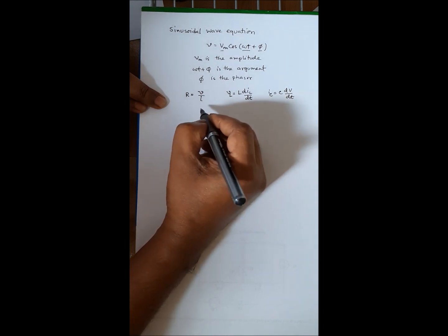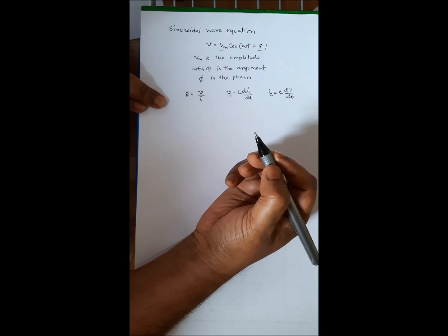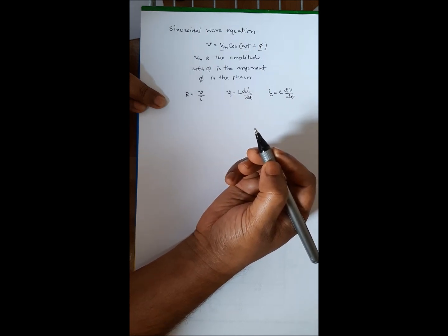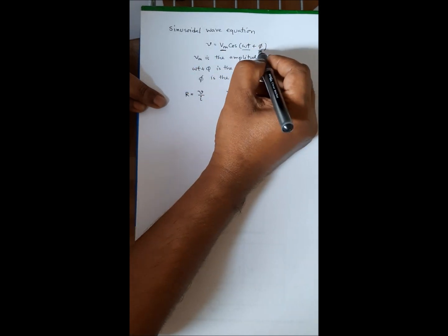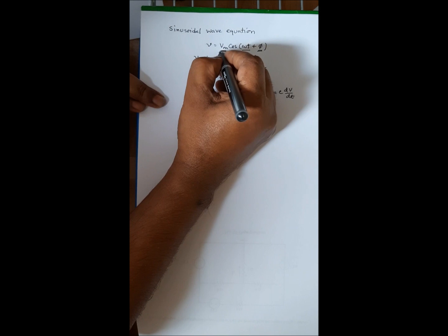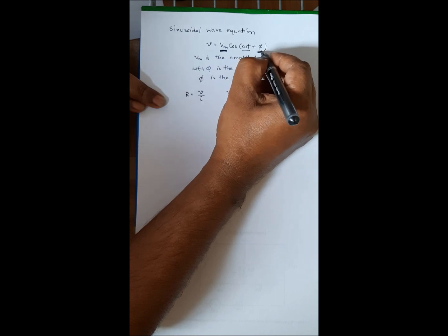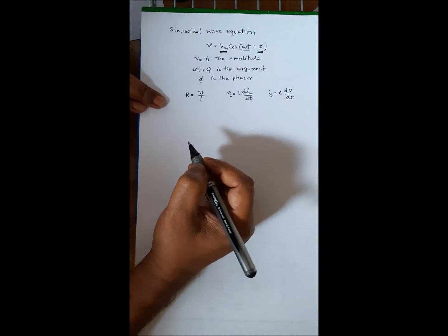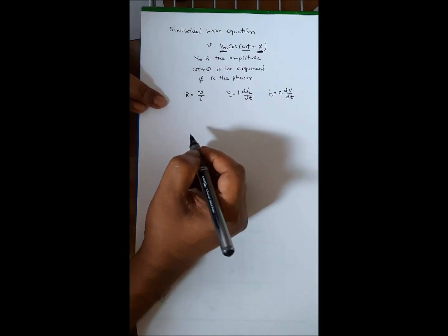So therefore, we don't need to consider three parameters for analyzing an AC circuit. Rather, we need to consider only two parameters, the amplitude and the phase angle. So it would be sufficient if we can find the amplitude, magnitude, and the phase angle of the response, then we can have the full information of the circuit response.